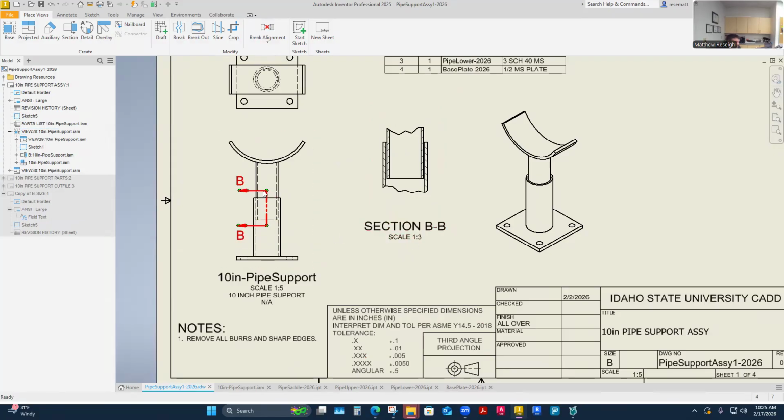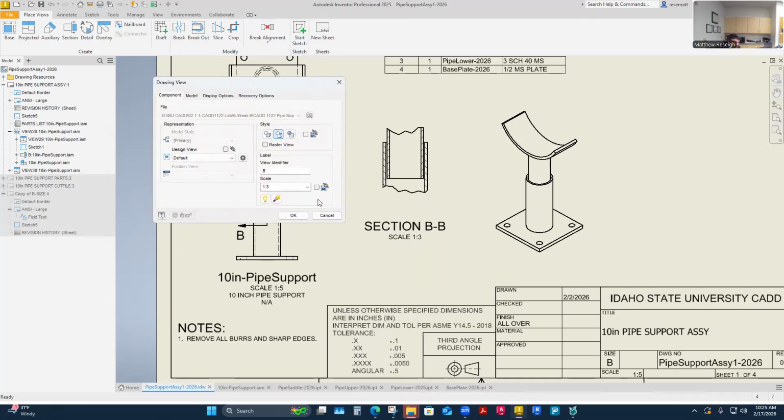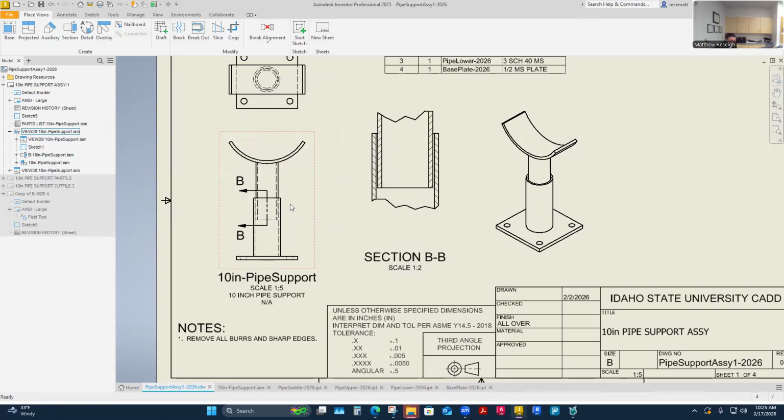Of course, it's really an unconstrained sketch that's actually holding this. I tend to keep these auxiliary and section views and detail views unconstrained, so I can kind of move them as I need to. I really try to avoid having auto constraints pop up when I'm dropping those. Otherwise, they just get harder to break away without getting into the sketch. But it is this sketch here. You can get into it and break those constraints if they happen, or you can delete them and start over. But 1:2 is maybe what I'm thinking now that I saw my drawing.